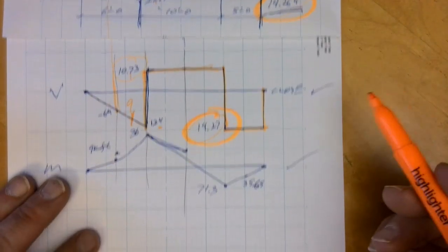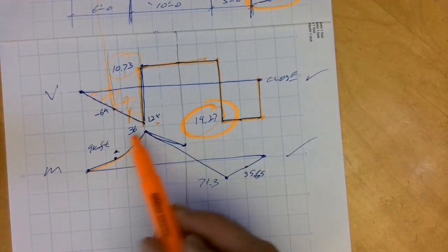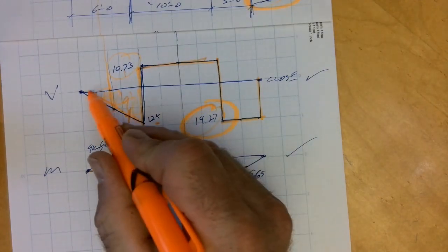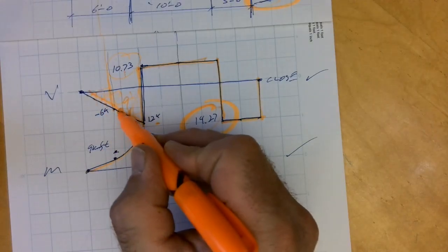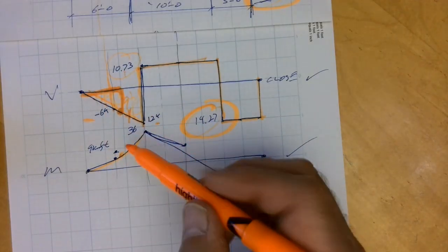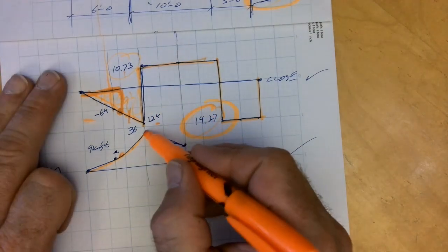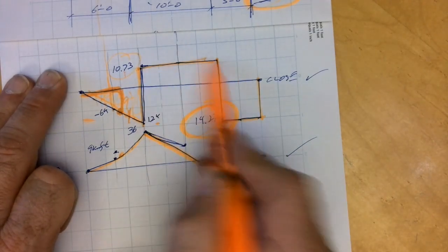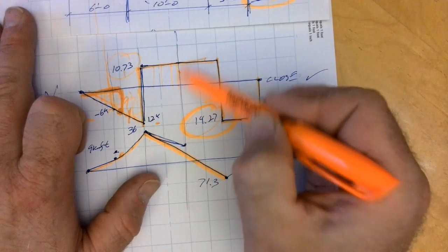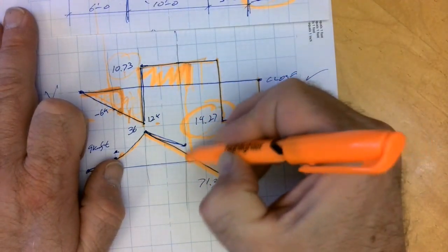Alright, for moments, now I'm taking the area of the shear diagram, and that's why this is a parabola, because this is a triangle. So I could come out here to any point along, multiply this magnitude by its correlating distance, divide it by 2 since it's a triangle, and that would give me the point. So I can do this at any point along here. Same thing here, and the reason this is a straight line is because this is a rectangle. So I can come anywhere along here, calculate that area. So let's say I chose that point, that would be my moment at that point.